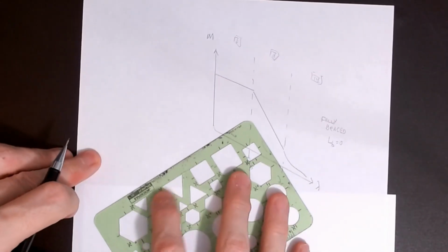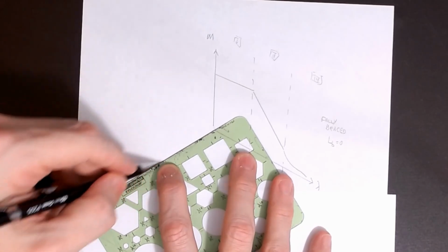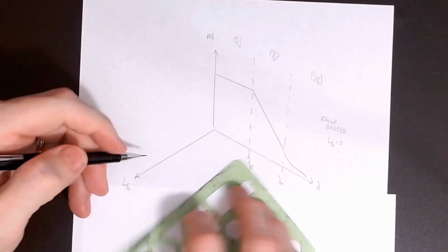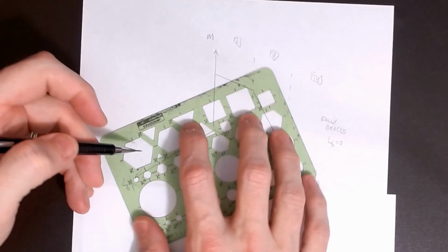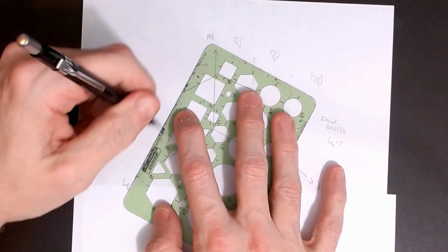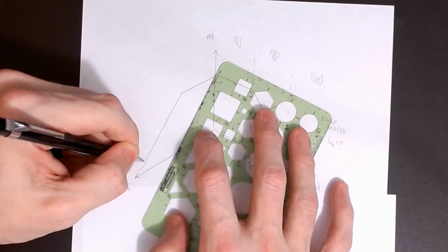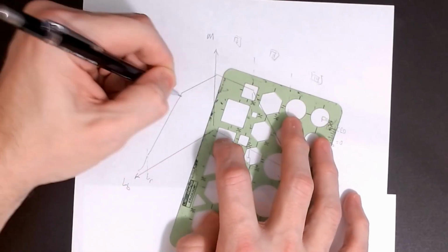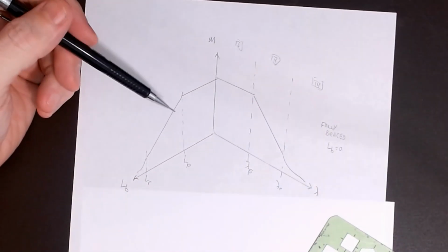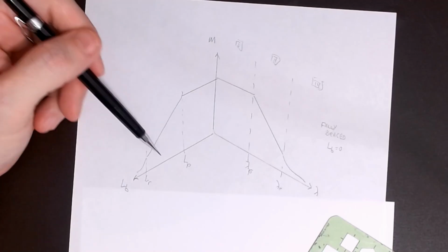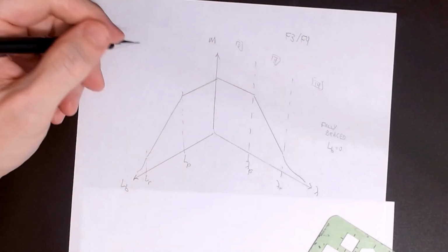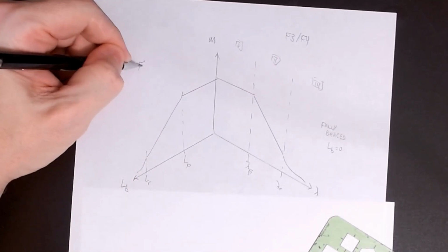On the other axis, I can draw this way. We can plot LB. Well, what happens if LB isn't 0? You'll start to see, and we'll talk about this when we get to lateral torsional buckling, you get another set of curves that look something like this, and down here this gets listed as an LR, and this gets listed as an LP. The two simple cases that we're going to work on are this section, which was F3, F4, and this side, which was F2.